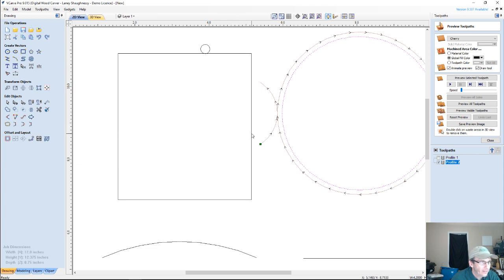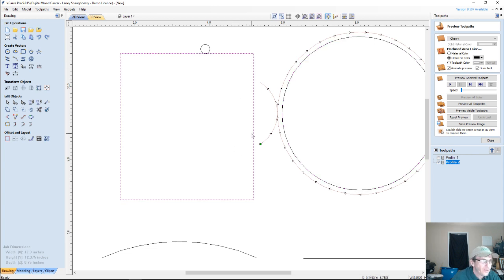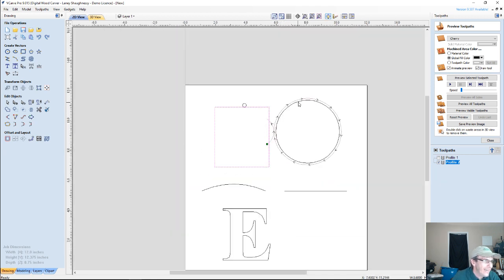My profile rectangle cut. But what if our spacing was closer together because it was text or something, like 2 letters and 2 words? We don't want our lead in and lead out to be in a main area. We want it to take advantage of waste area.